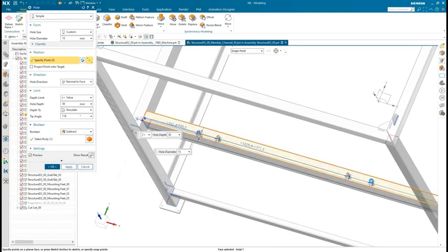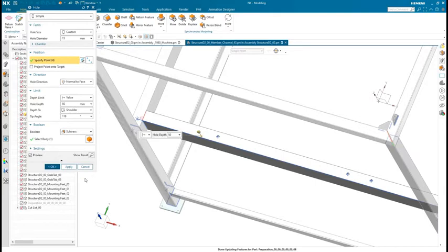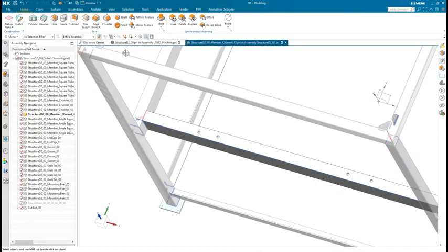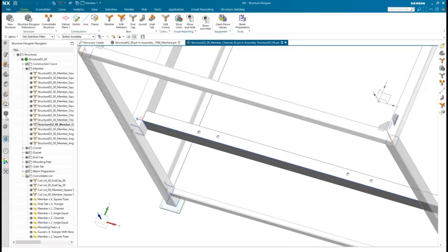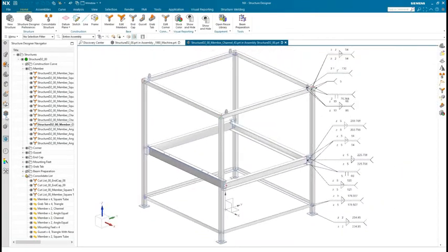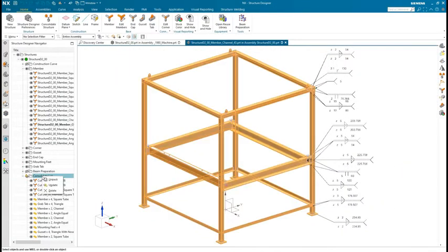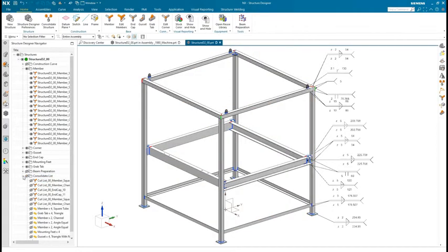Once the holes are placed, it's a matter of rerunning the consolidation process. The consolidation operation looks for geometrically identical parts, and if a part is, say, mirrored, the system is smart enough to consider them different. Because of the newly added holes, this member is no longer geometrically equivalent to its counterpart. Watch as the process removes this component and places it in its own group. A quick selection of the members shows it's now a unique component.